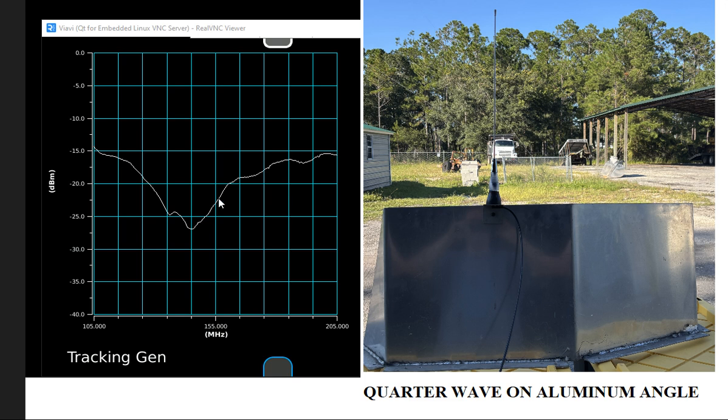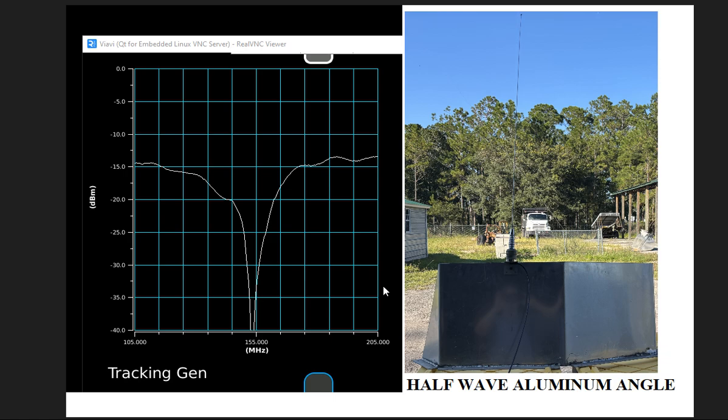So this is, like I said, now you're going to have to cut this at an oddball length that's not going to match the cutting chart to get it back over into the right position. So if you take a look at this same setup here, except now we're using the half wave. Well, the half wave antenna isn't affected with its resonant frequency being shifted, but